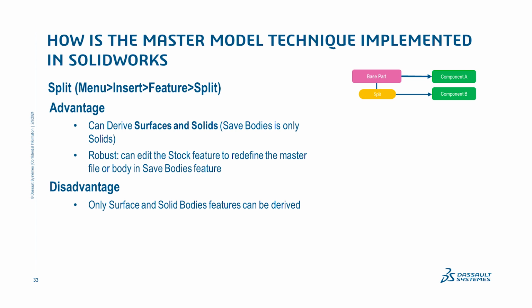How do I use it? Well, I'll use it occasionally where my master file is pretty much the part itself, and there's maybe one part that needs to be derived out. Let's say it's a housing with a battery door, and the battery door is the only other part. Well, I'll use a split surface to just split out that part, and now I have component A, my housing, and B, my battery door.